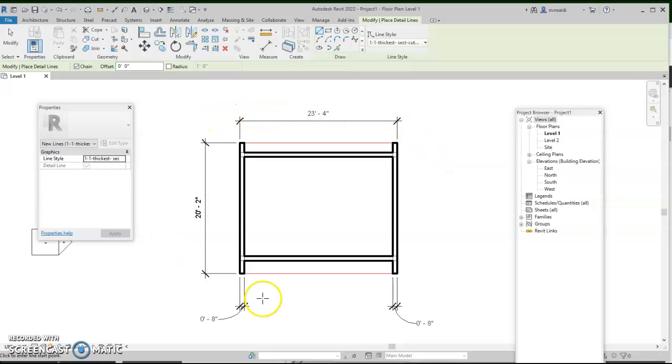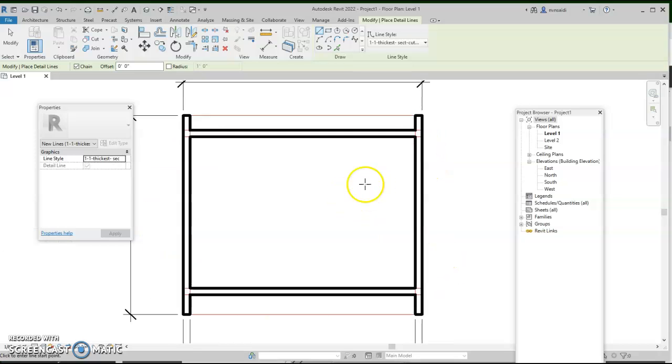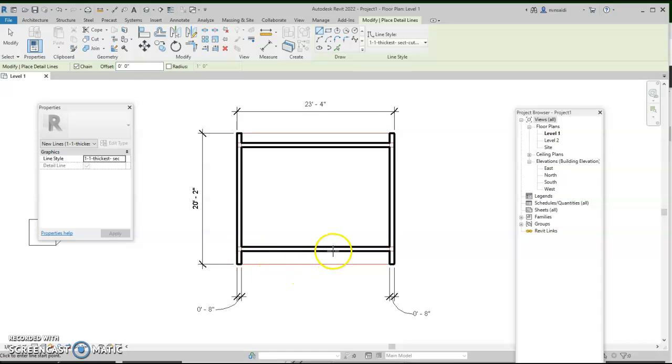Watch this. I went over my red lines and dark lined the area of the lines that I can actually see. I leave my red lines alone. When you are drafting manually, you do the same. You draw very, very light lines, and later on you dark line over it without having to erase your light lines.